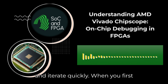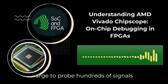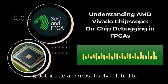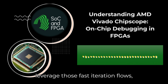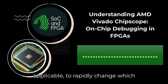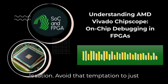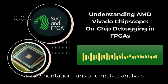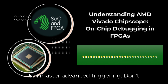Fourth, start small and iterate quickly. When you first detect a failure on hardware, resist the urge to probe hundreds of signals immediately. Instead, start by probing a small, targeted set of signals that you hypothesize are most likely related to the failure. Be focused. Then, leverage those fast iteration flows, incremental compile, or the ECO flow if applicable, to rapidly change which signals are probed as you gather more information and narrow down the bug's location. Avoid that temptation to just throw every signal into a giant ILA. It usually just slows down your implementation runs and makes analysis harder. Iterate intelligently.